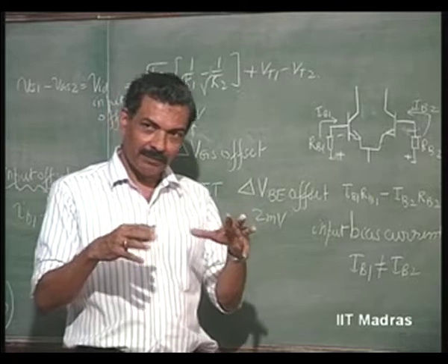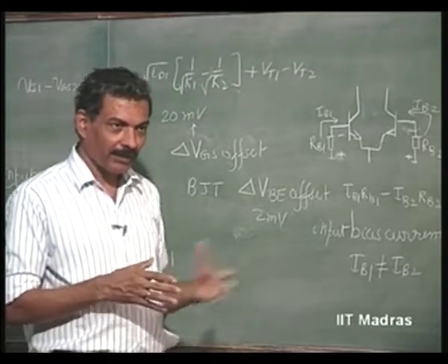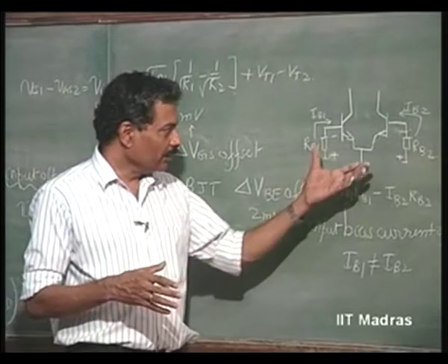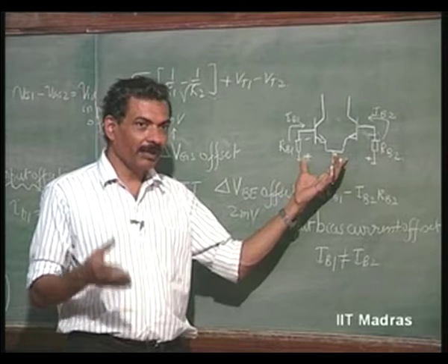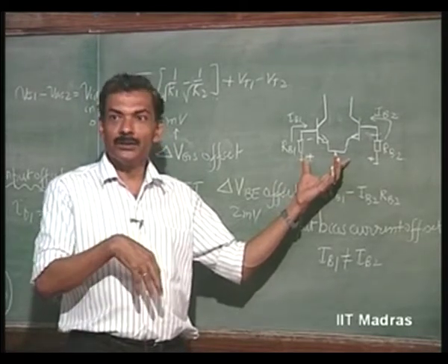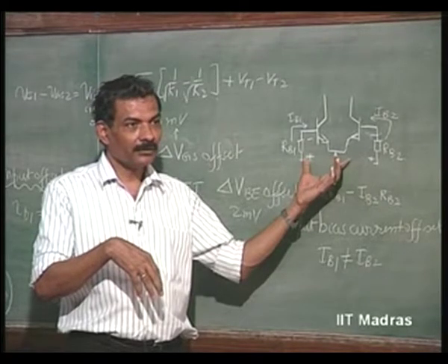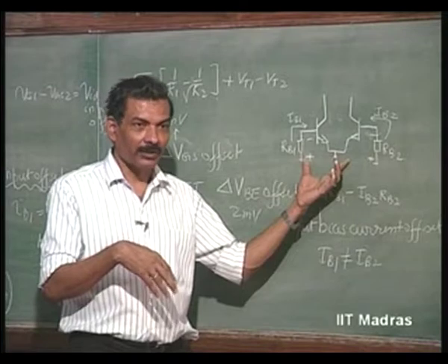So, application depends upon the source that you are going to choose. Whether this amplifier is going to be MOSFET input or BJT input depends upon the source impedance, and whether it is a low frequency application or not.